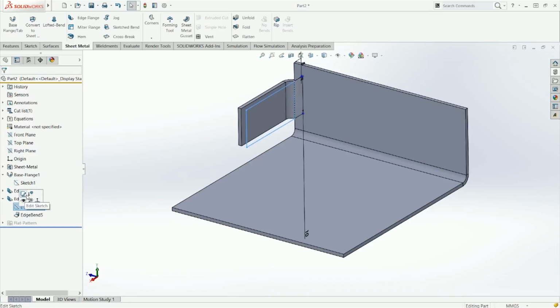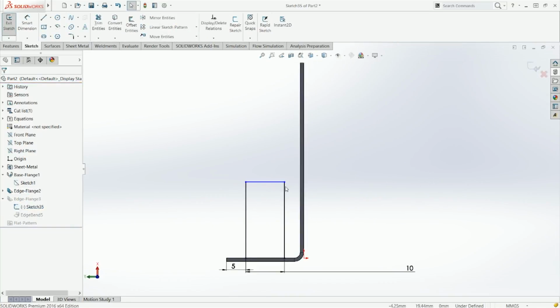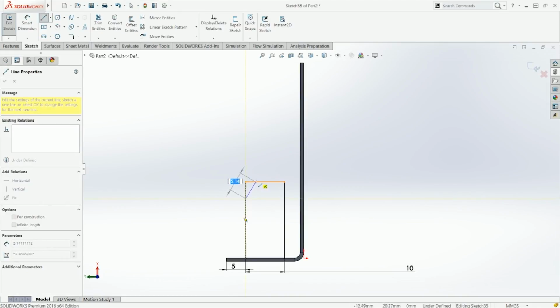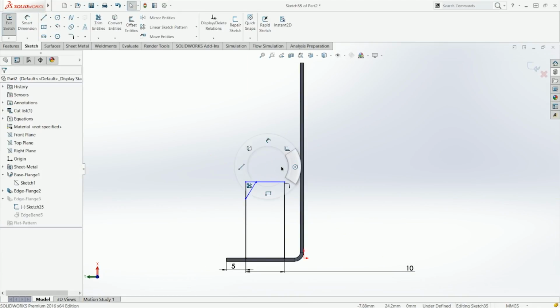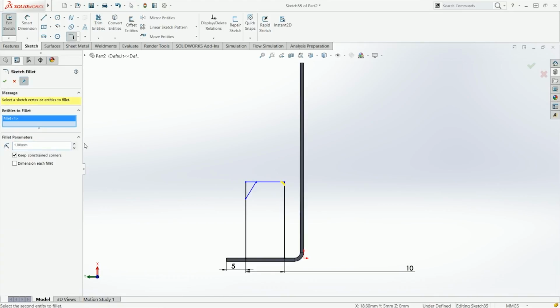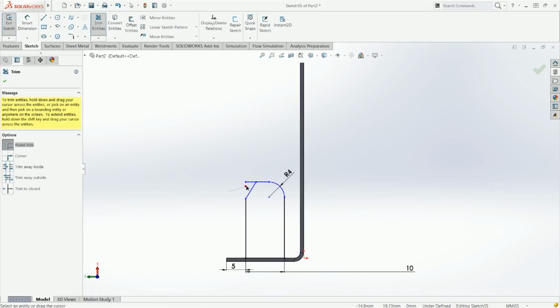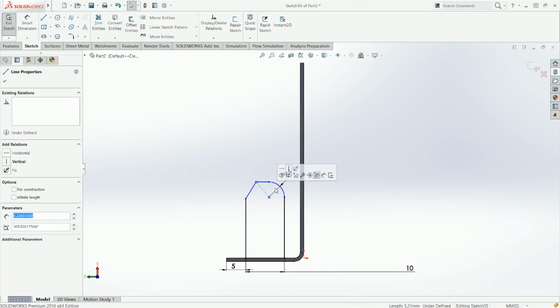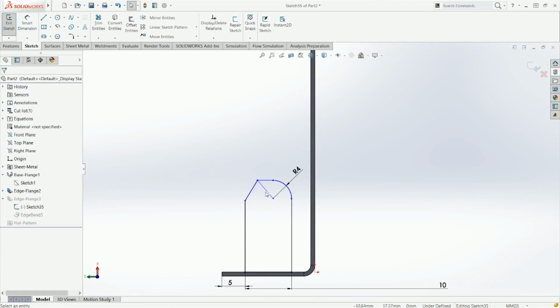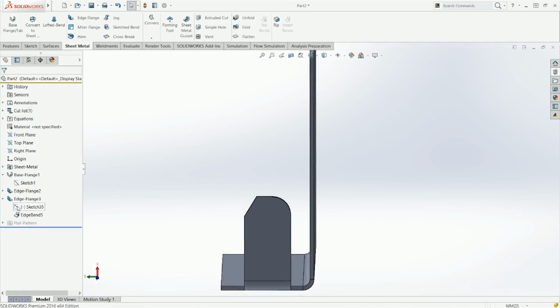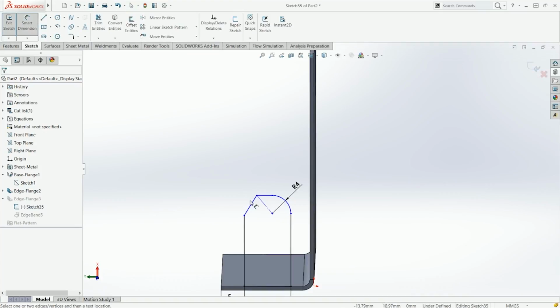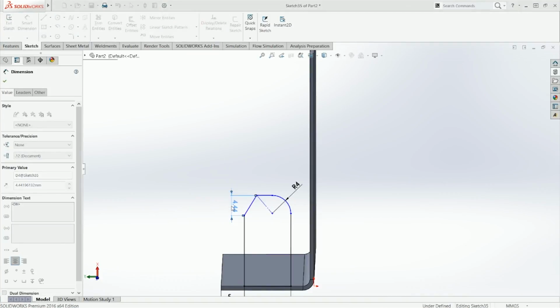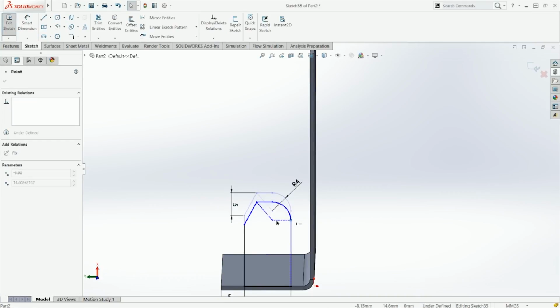So also, you don't have to create a rectangle or a square. You can select pretty much any shape that you want, as long as it's a closed one, obviously, and it's a complete contour. You can have construction lines if you want for reference, but nothing else. So if I get rid of that, as you see, I will still define this just because I need to.